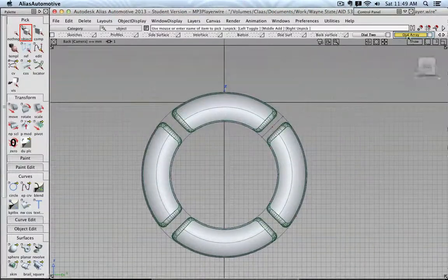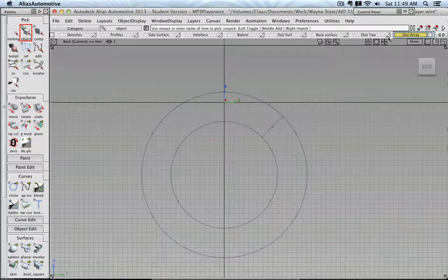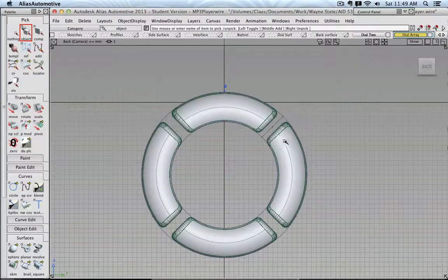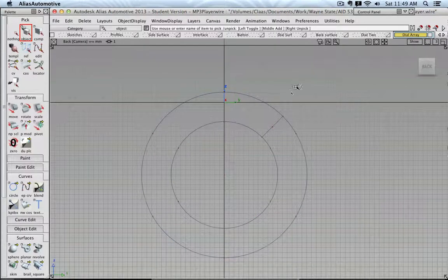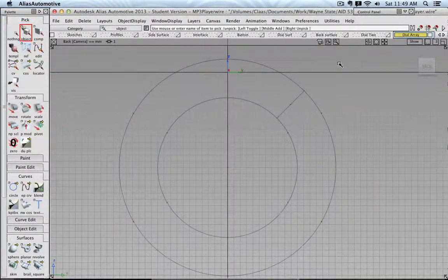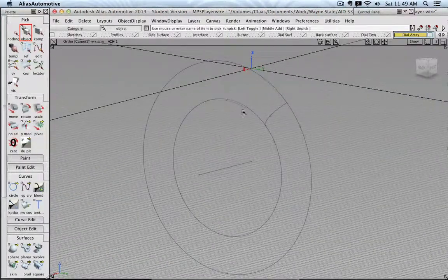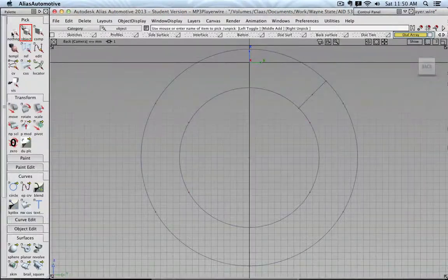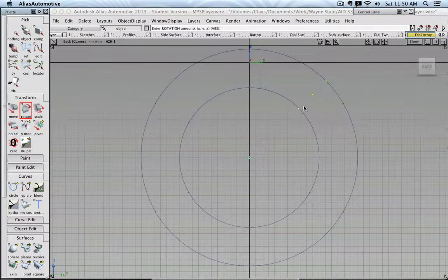And I would like now to have an approach where I only have one dial and then interactively I duplicate it. So here is my sketch, and I have my two outer rings. I drew in a center line for me so I can see the rotation center point, and I have, for example, here my arc. Now this arc I'm going to copy and paste, rotate it 45 degrees to the other side. So I type in 45, 0, 0 and press enter.